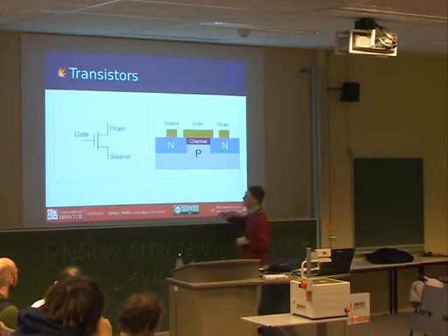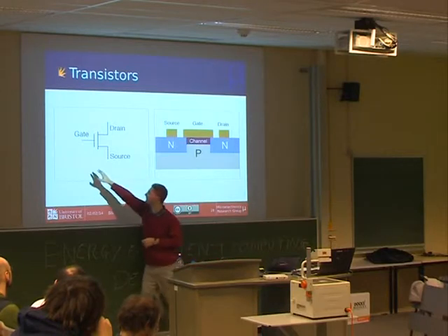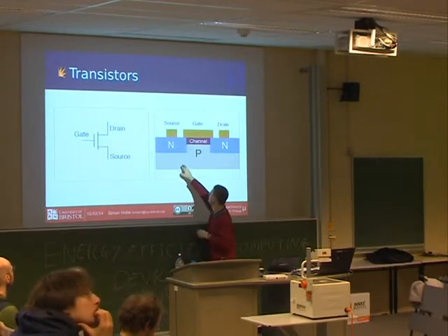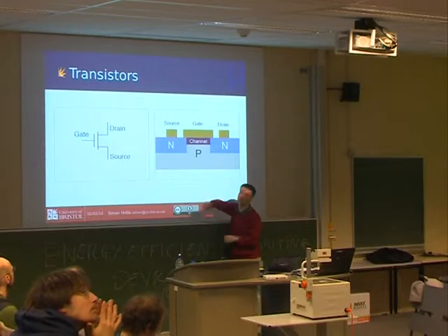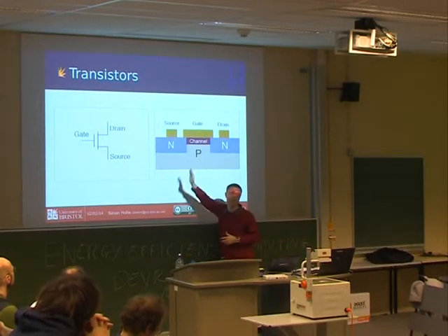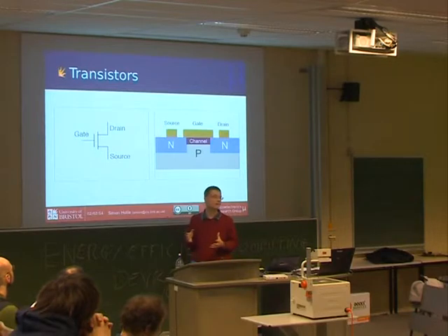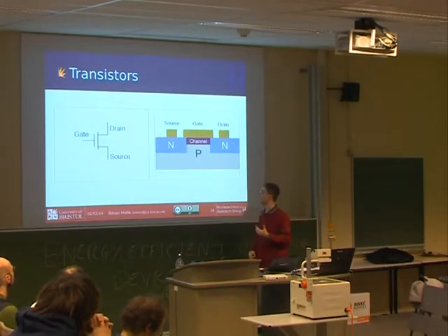And the idea is that this transistor will be able to be switched according to a voltage on the gate here, and if it's switched on, current passes between these two blocks of N-type silicon, and when it's switched off, current's not able to pass through that area called the channel, and that's how it turns off. So this is a device you can turn on, you can turn off, based on the voltage from the gate. And if you move the voltage from the gate, you will dissipate power.